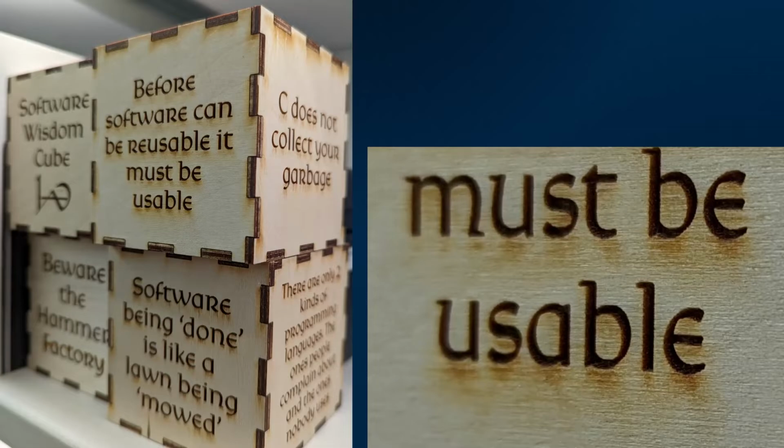Another thing to note, here we're seeing engraving in text, and it looks great. The actual surface that's been engraved is very, very rough. So here we see the M in "must" in the right-hand image. If you were to zoom in there, you would see that it's really, really rough down there. Sometimes people have this idea of, well, could I use the laser to cut vertical curves by altering the power of the laser? Not really. It doesn't work super well. There's also focusing issues with the laser. So just remember that if you're cutting something with the laser, the actual specific depth that it gets to is extraordinarily hard to control. So it's not something we normally try to do with a laser.